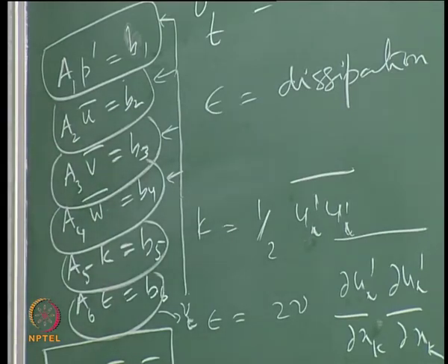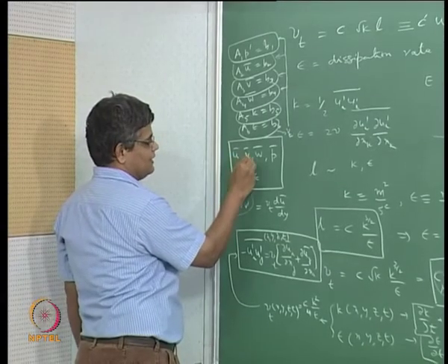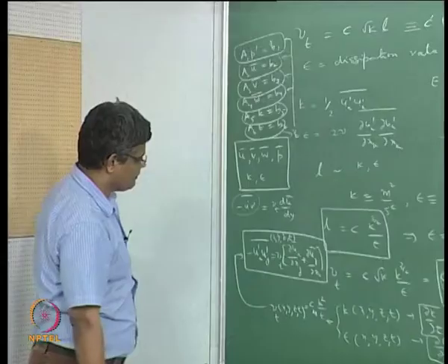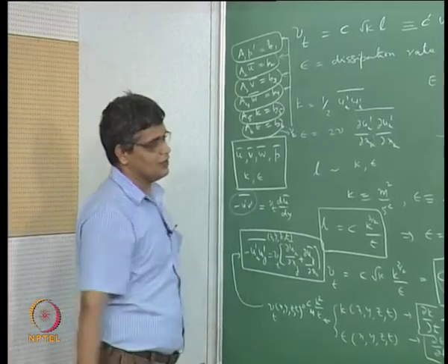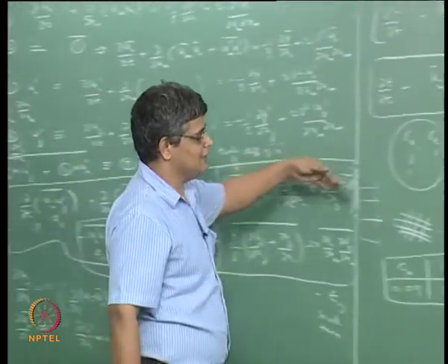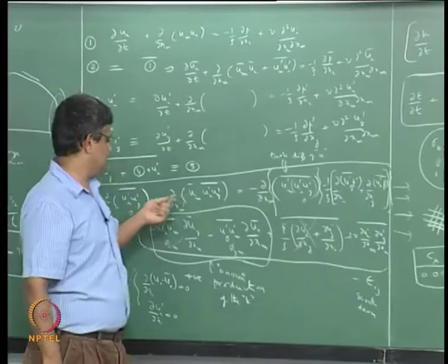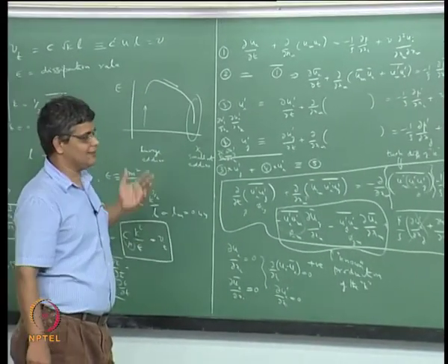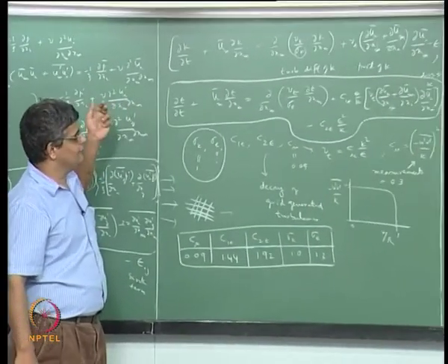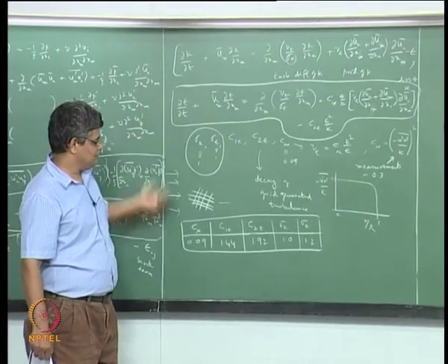So we can do each of these things sequentially, that is one after the other, and update the values frequently with an under relaxation and get an overall evaluation of the time average velocity components and the pressure and the local time average quantities representing turbulence, k and epsilon, from which we can determine the diffusivities and so on. So this is how a two equation model of turbulence works, and what we notice is that these conservation equations do not require specification of the mixing length or turbulent viscosity or anything like that. These are self-consistent contained equations, and there is no more need to say anything other than the fluid properties, the flow domain, and these constants.